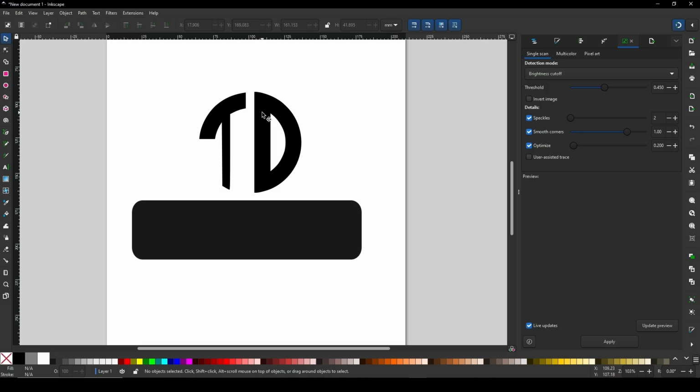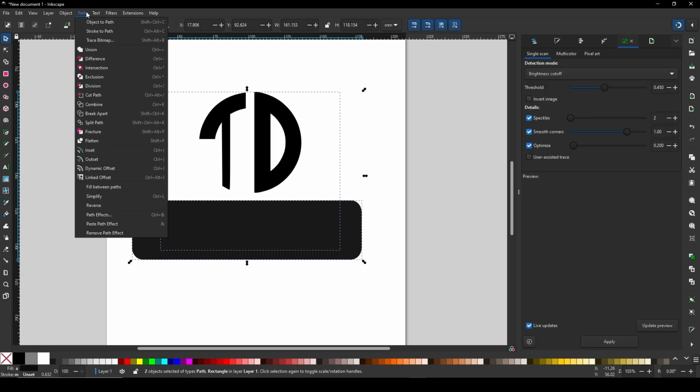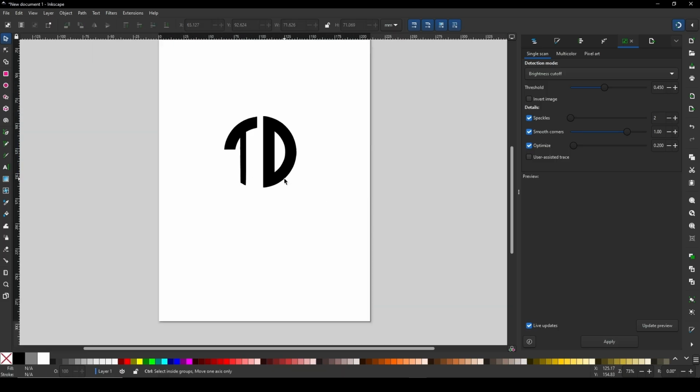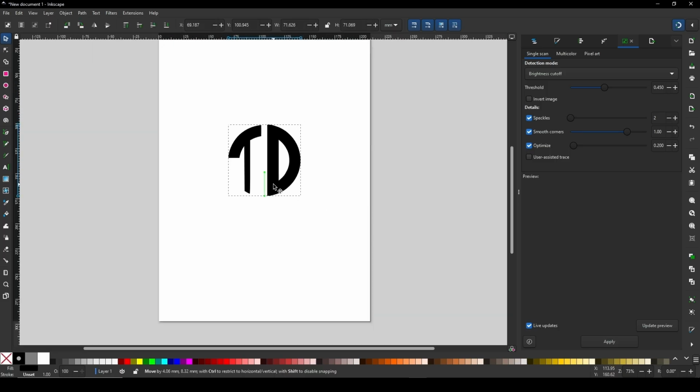Next, you shift-select the logo first, and then the rectangle later. And I'm going to do a Boolean cut. So I go to the Part workbench, and then Difference. Okay, and you can see I just removed the text down below.